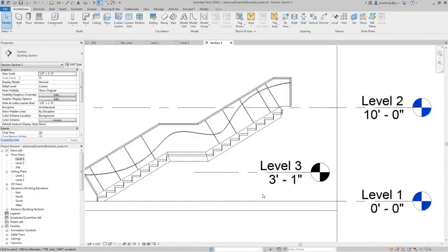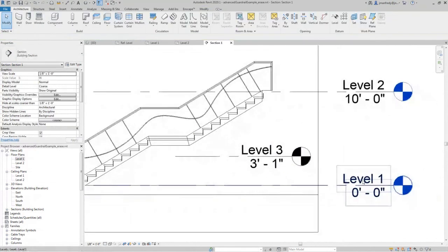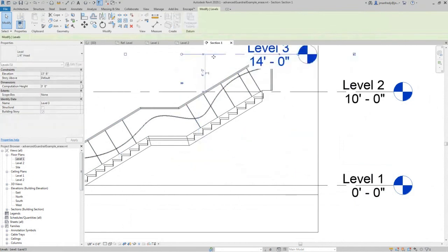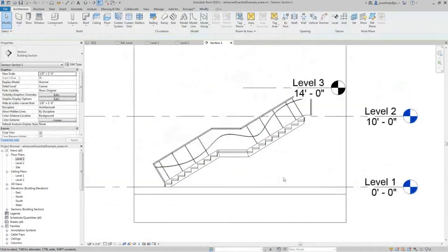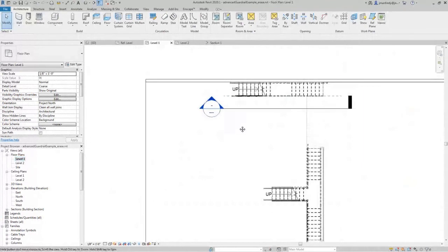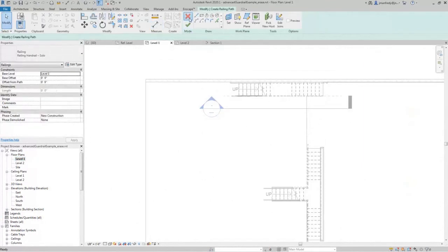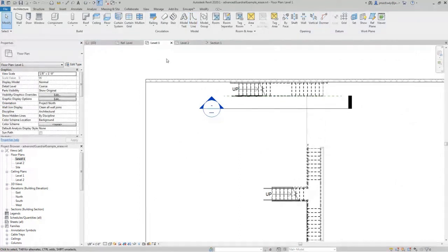And when you make a stair, you can tell the stair to go from this level to that level there. See? Because making these level tags, wherever you decide to put them, allows Revit to draw a stair to that place, even though that's not a floor plan. See, it's black because I unchecked that box. I can then draw a stair in Revit that communicates with that level tag.